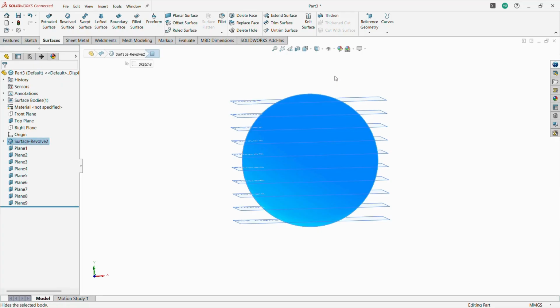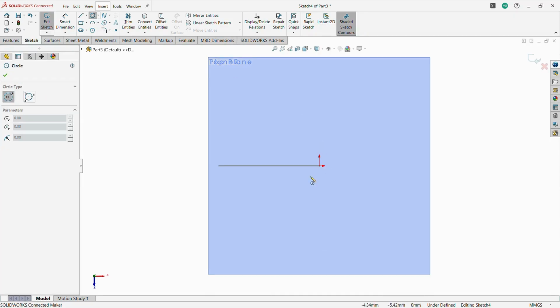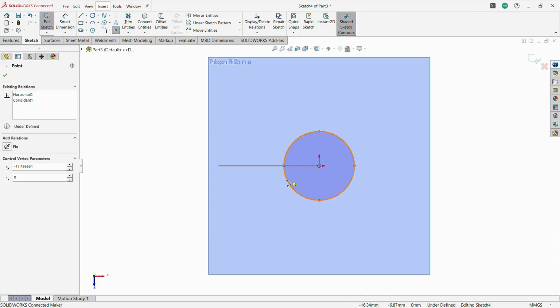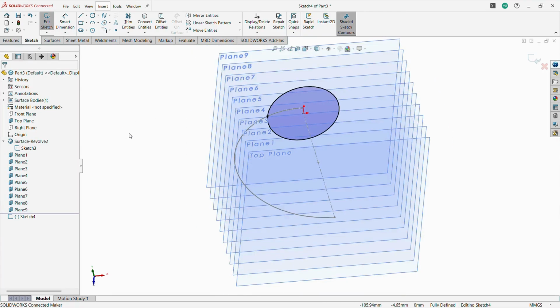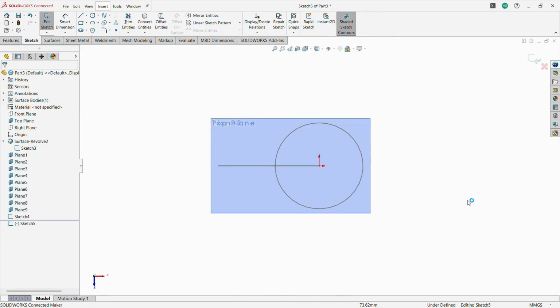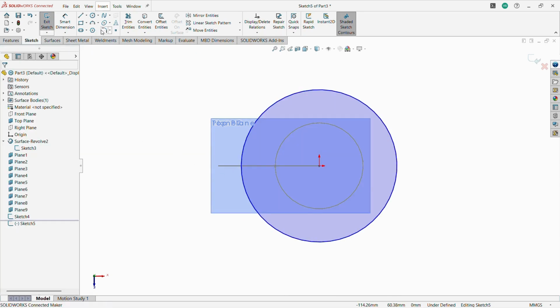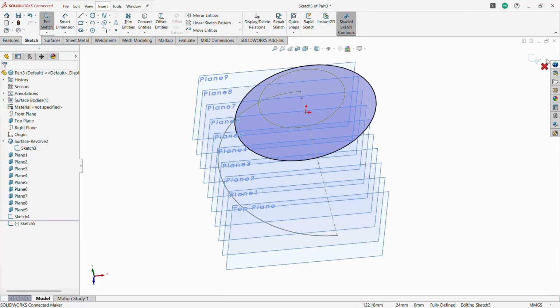Next, show the revolved sketches and choose each individual plane, create a sketch, and draw a center point circular profile. Now under Point, specify this point. Now choose this point, then make it coincident using the Pair option to mate with this opposite 3-point arc profile. Again, select this second plane and draw a center point circle, then initiate a point and make it coincident using the Pair option; it must be coincident to this open arc profile.